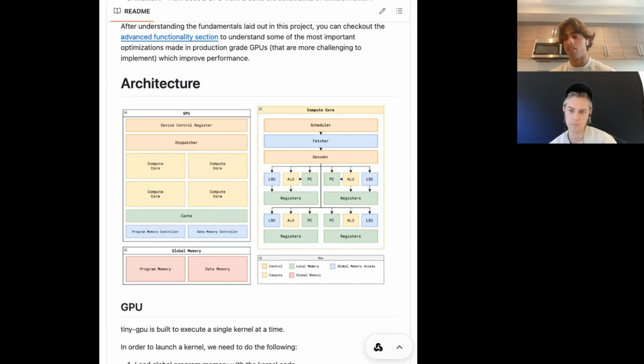For example, when writing code in Verilog, knowing how many gates a piece of code actually translates into is important. Like for me, I might just write the divide sign as my division instruction. In reality, nobody would ever do that. The divide sign actually turns into a gigantic piece of hardware, which you would never actually want to use. You wouldn't actually want to implement division as an instruction. So it's things like that.